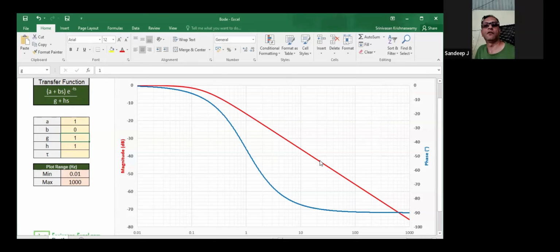If you ask that to me as a control system engineer, what you would then do is try increasing the linear region of the system. That can be done by adding certain nonlinear filters, or certain nonlinear feedbacks, in order to increase the linear range of the system, so that your system begins to appear linear for a larger range. So you add another nonlinear component that cancels out the nonlinearity in the original component.